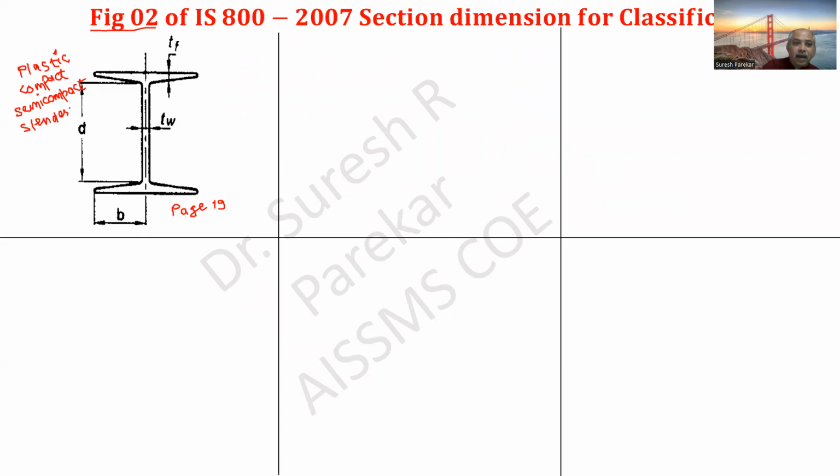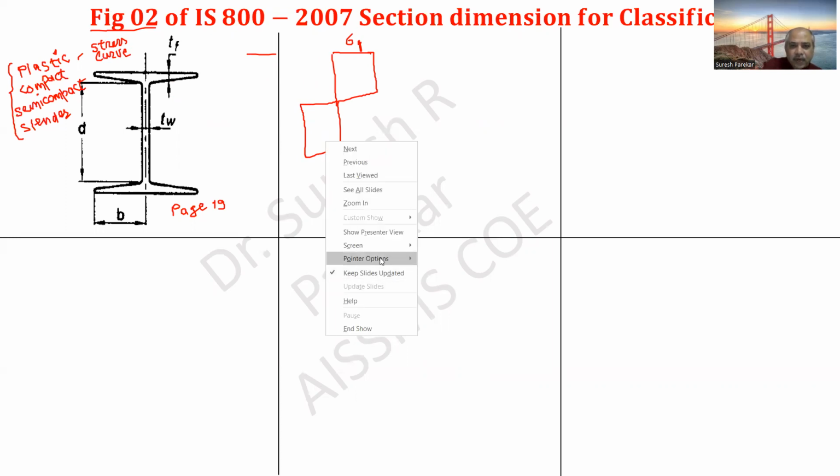Now he may ask on which basis you decided the section. We have decided this on the basis of your stress curve. If you remember plastic analysis in structural analysis 1, there all fibers are at the value of sigma y, the whole section. If I draw this section and plot it here, it becomes easy for you to understand.